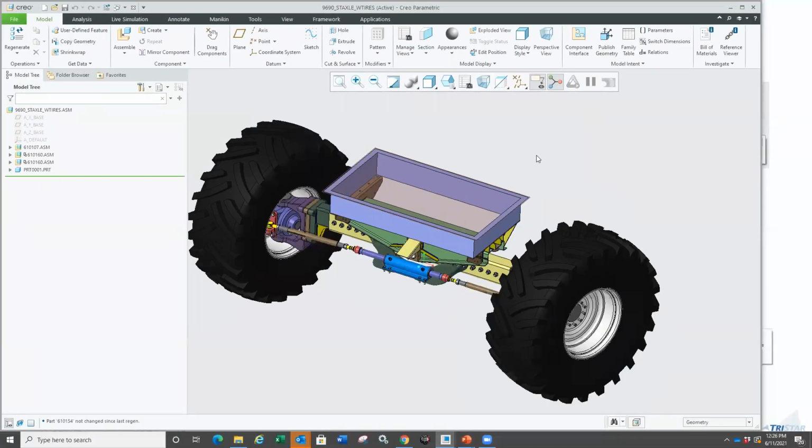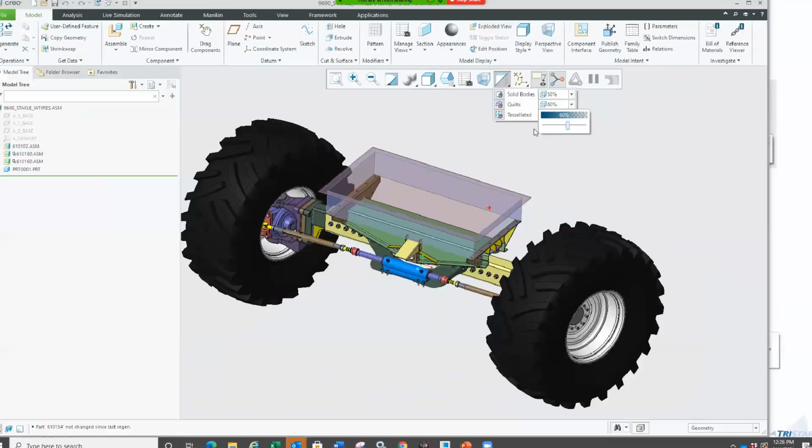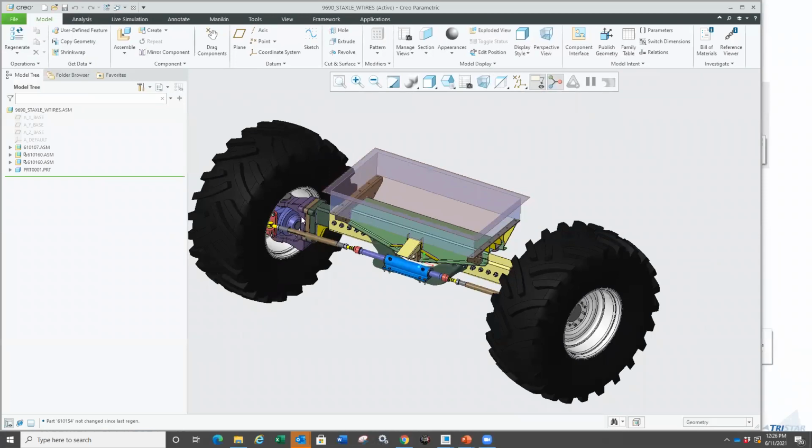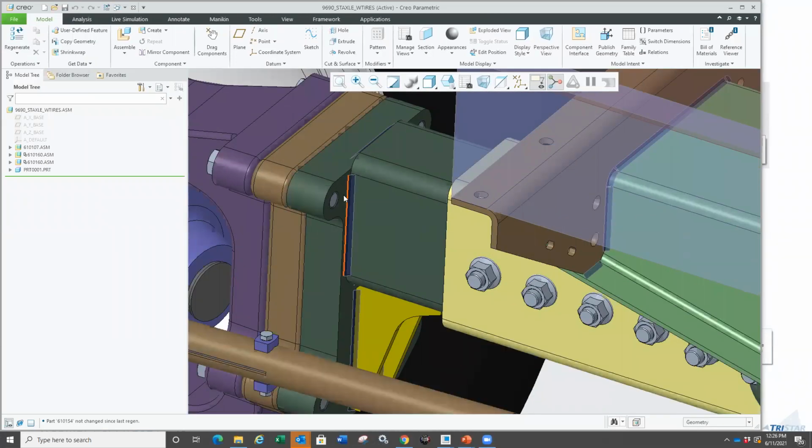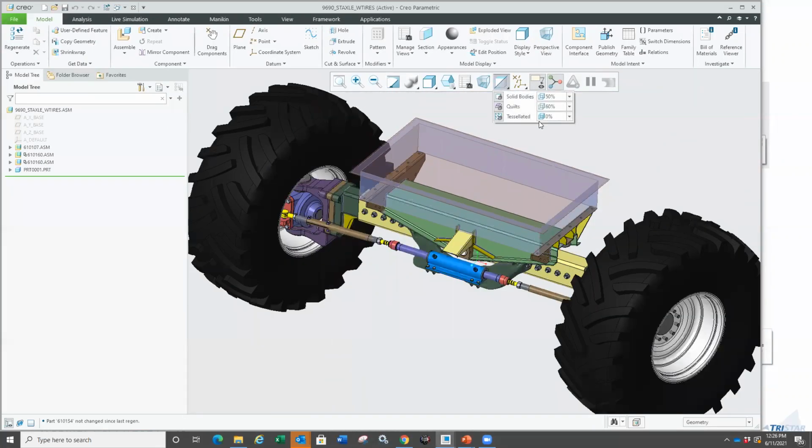So what I could do right now is go in here and, for my quilts, enable transparency or disable transparency. Once I enable them, I'm able to just drag them out. As I'm dragging it, you could see this is the quilt I have, a surface quilt. I also have a few welds in here that I've done as a surface weld or a solid weld. Even those go away when I set it to 100%, and I can control the opaqueness, how transparent it is. I can control that for quilts. Right now, I'm going to leave it at 0.